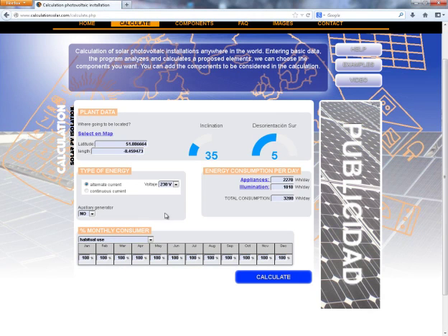If we have or would like to have auxiliary energy, we can select this tab, which recommends the minimum output of our generator. Then we can choose the percentage of consumption by month. For this purpose, we have a new window in which we can select between the following options: common house, weekend, or summer and winter holiday house. We can also adapt the percentage of use by months, adapting it to our necessities. In this case, we are going to choose holiday, July, August.